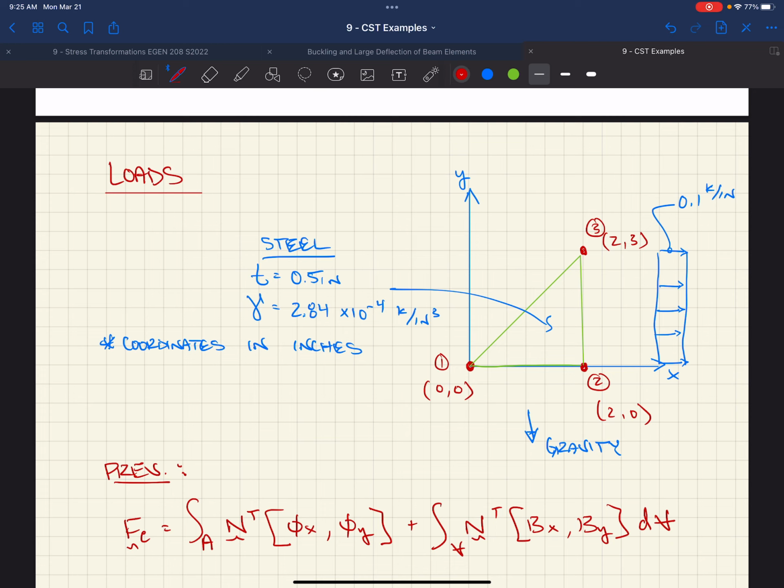Would we just do a line load? Is there any other loads you might apply in that case? If we had a shear wall, something like this, coming down, it has multiple stories above it, right? It's got big shear force acting at the roof and at each diaphragm up above. And then this wall sits on a diaphragm. We would put a line load on that diaphragm. Is there any other loads we might put on that diaphragm that this wall might impose on that diaphragm? Dead load, okay, that would be good, right? Vertical, uniform load along the length.